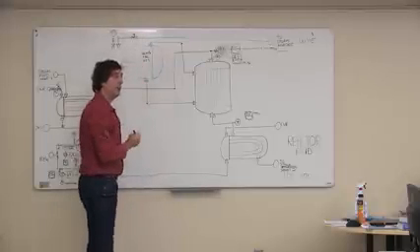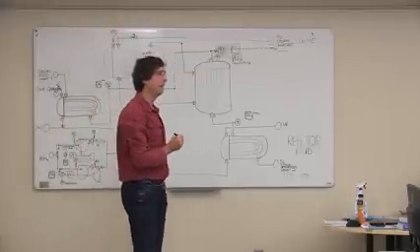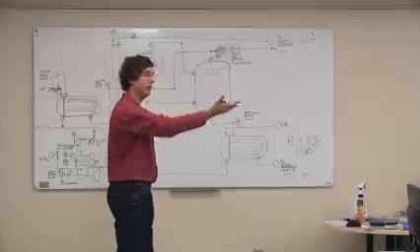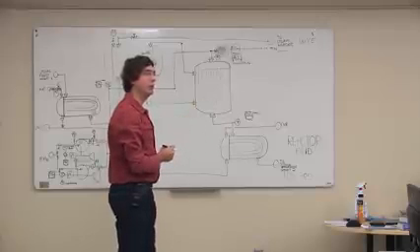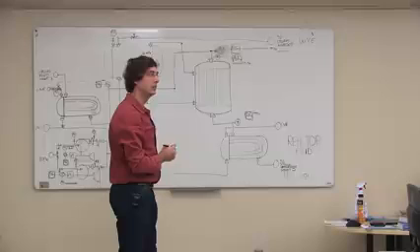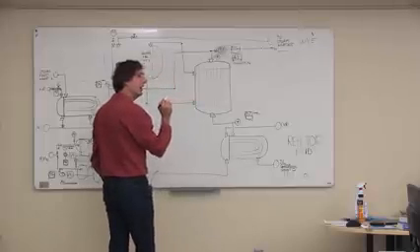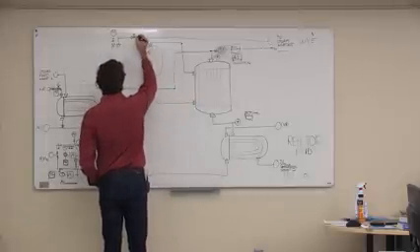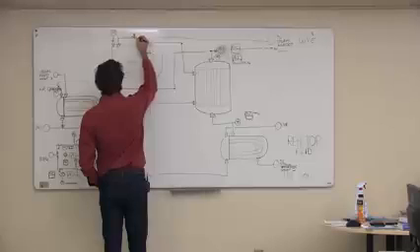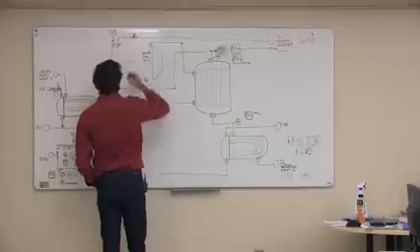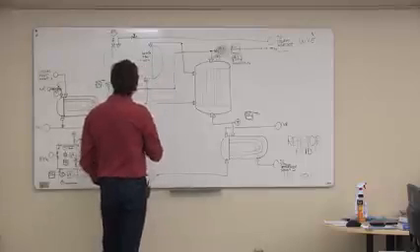Do we want to fail it open or fail it closed? You think fail it open? Who thinks we should fail it open? Who thinks we should fail it closed? Only one person's willing to stick their neck out on this one, eh? Well, let's try it as fail open, and we can come back and look at it from a hazard analysis later on. So fail open by putting a little arrow sticking up there.